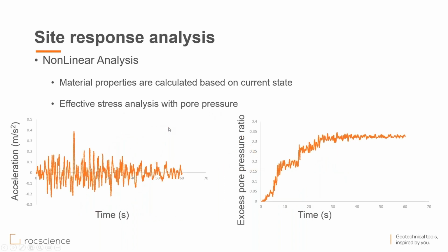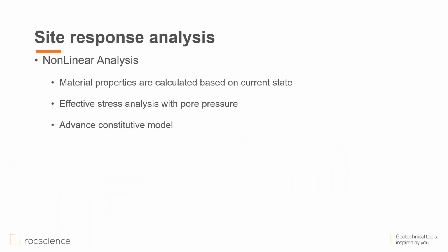Another property of the approach is that we can use effective stress analysis with pore water pressure, and that's why we can easily model excess pore water pressure buildup using this approach. And of course, you can use many advanced constitutive models to model more realistic behavior.